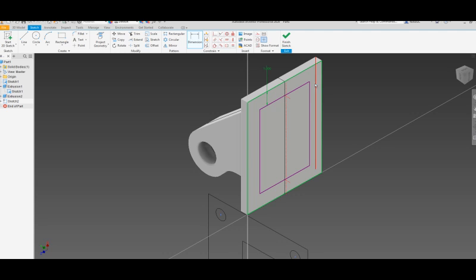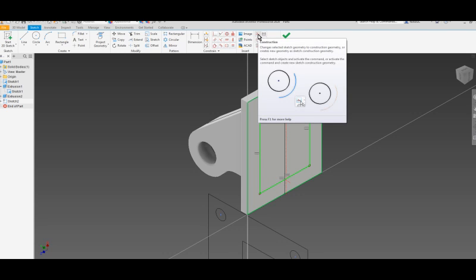Now the geometry itself has to be there. It doesn't necessarily need to be converted, but I like doing this. Why? As I explained in class, geometry that is continual and solid is able to be converted. We don't want it to convert. We just want this to be an anchor. So how do we convert again? Well, if I click and hold Control and click around all 4 edges, I can then turn them into construction, which is right there.